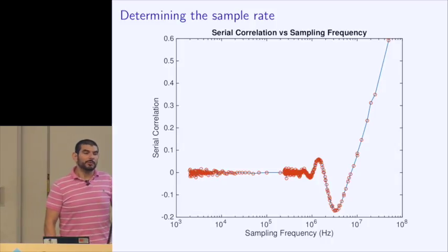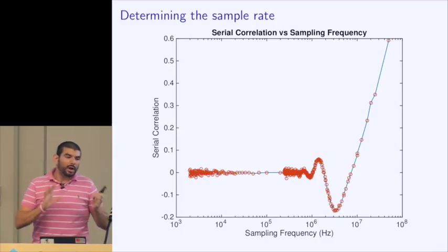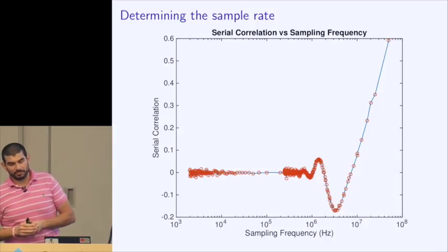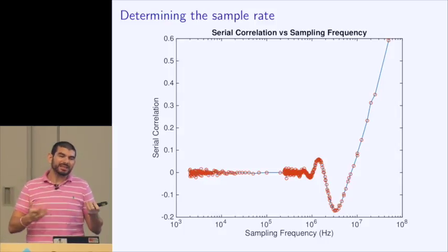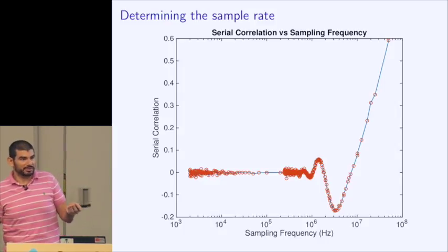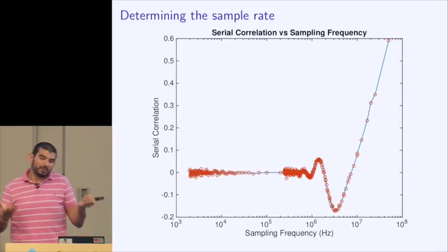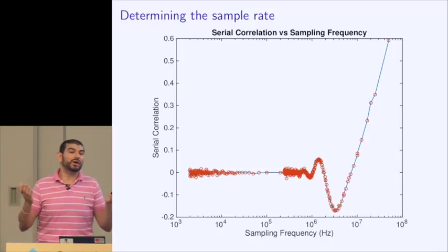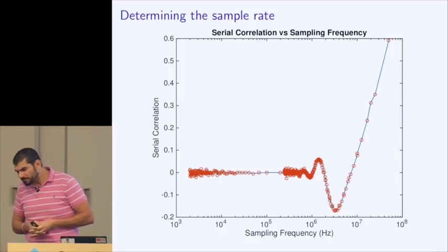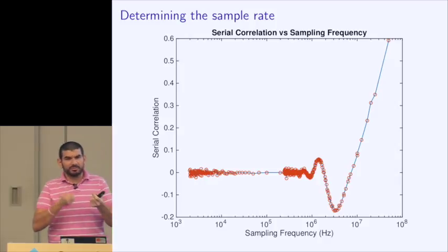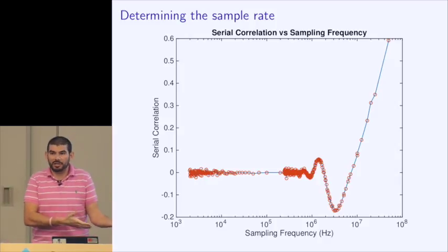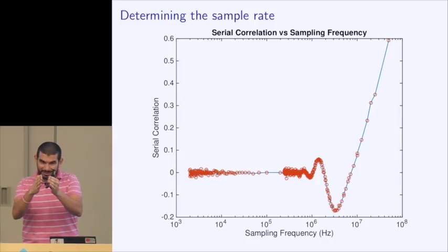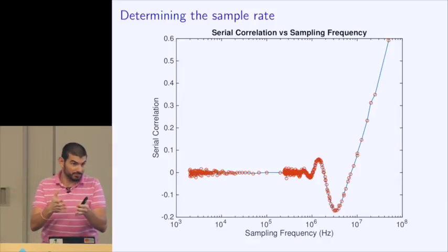All right, so the other thing to think about here is, why is it that we have to worry about the sampling frequency? Well, the comparator that we use has some limited bandwidth, right? It's not a perfect device. And in particular, let's say its output can switch at maybe 10 megahertz or 5 megahertz or something like this. So what that means is if I sample very, very quickly compared to 5 megahertz, then of course the output can't have changed, and therefore the two samples that I've just taken are highly correlated to one another.